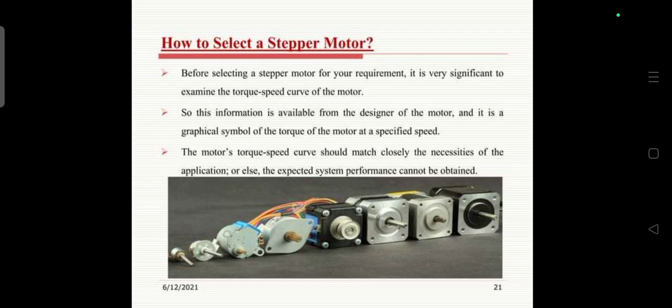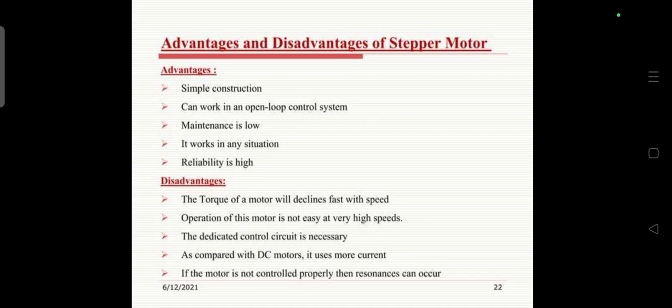Then, how to select a stepper motor? Before selecting a stepper motor for your requirement, it is very important to examine the torque speed curve of the motor. This information is available from the designer of the motor and it is a graphical representation of the torque of the motor at different specified speeds. The motor torque speed curve should closely match the necessities of the application. The diagram shows the various stepper motors.